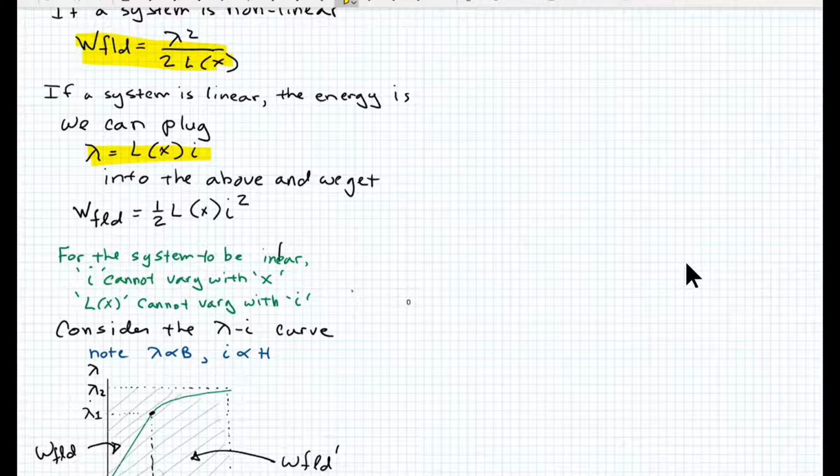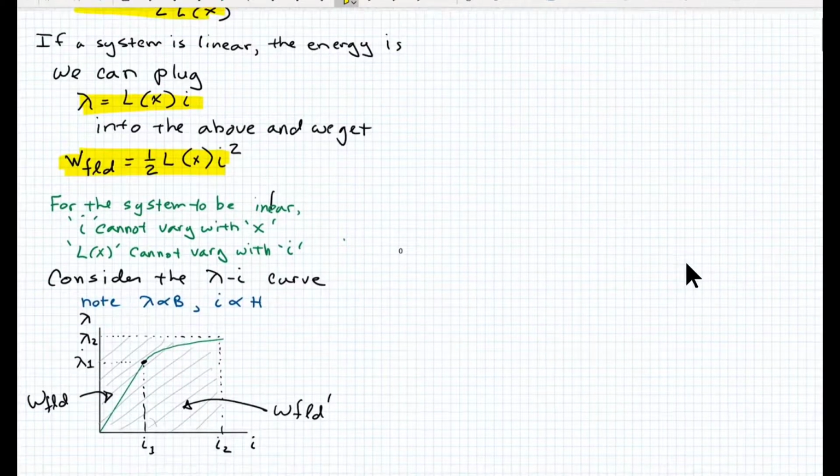I'm trying to get almost all of chapter 3 wrapped up except multi-winding, maybe if I could get that far. So I'm going to talk kind of quickly here. But we derived the force last time from the energy, and force requires movement. That's why we have this position dependency of the inductance. So once we plug that in, you get this somewhat familiar expression of 1/2 Li squared, where the L has X dependency. Now, if the system is linear,